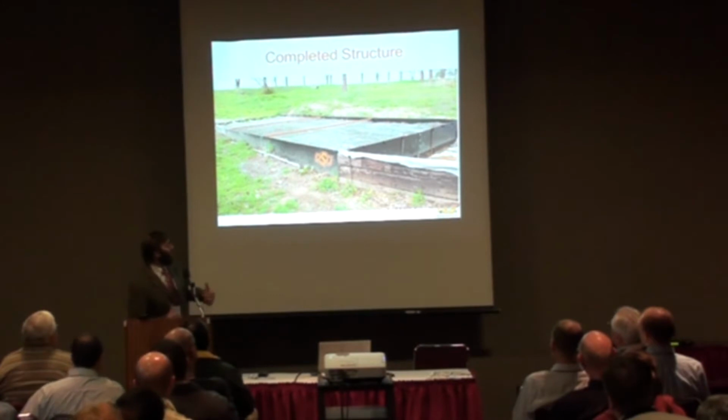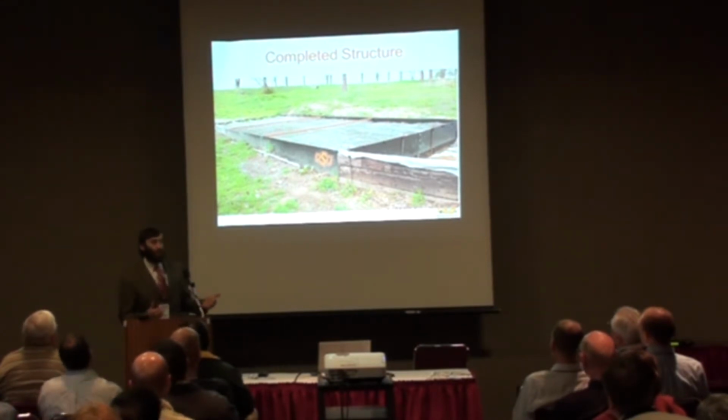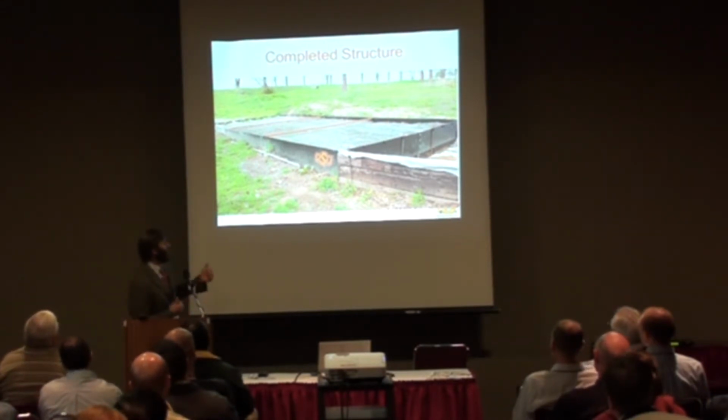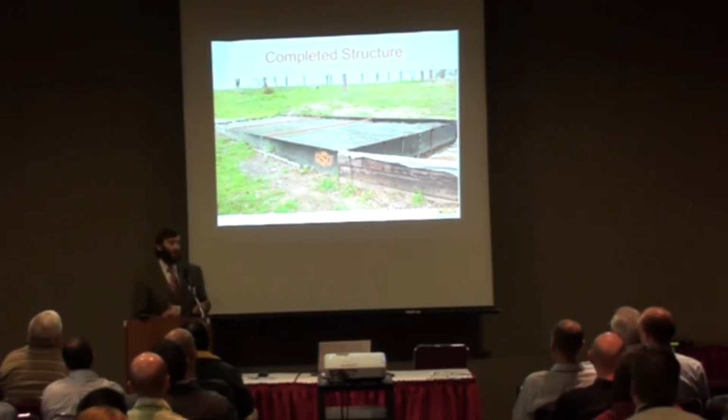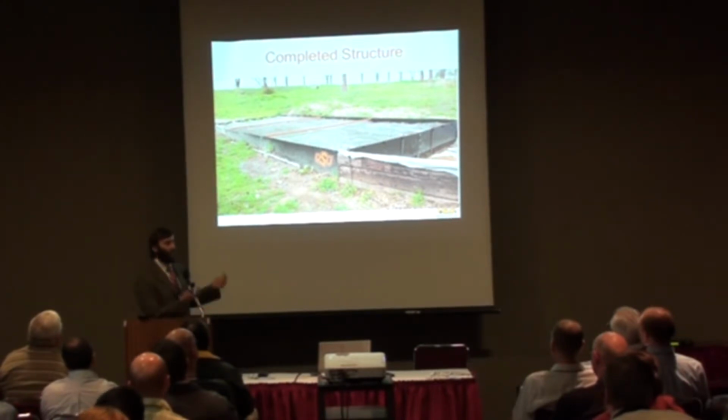We constructed this in modular form, 1/4-inch carbon steel, bolted together in the field. That bottom part, the gate, is designed to be removable, so you can lift it out when the material is spent and no longer removing phosphorus. Then you can drive into it with a front end loader of some sort, scoop it out, and replace it.